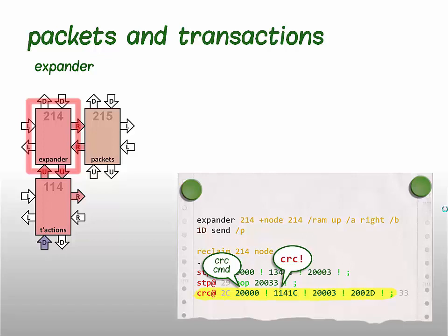Then there's a command for encoder to generate end of packet. And finally, we execute another command in encoder word rx which sets transceivers into receive mode because we expect a handshake packet from the device.